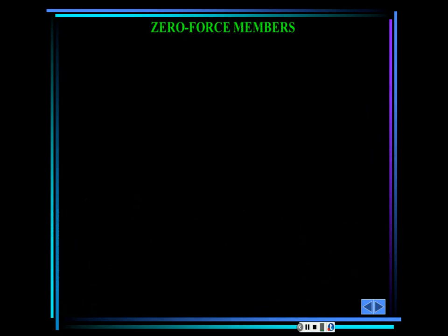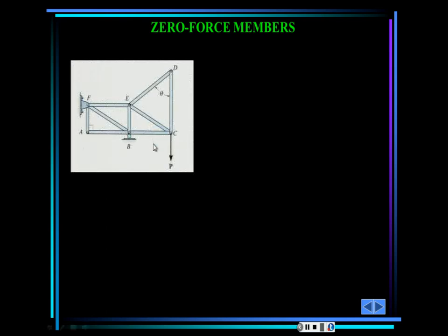We also covered zero force members last class, and we said that we have trusses like this, and suddenly you have this situation like this joint D. If you realize, here at this joint D, we isolate it and do summation of forces in X, there's no force in X, just this bar. That means that bar should be zero, and hence that bar also should be zero. Those are zero force members. And I showed you a really big example on zero force members, and also two rules.